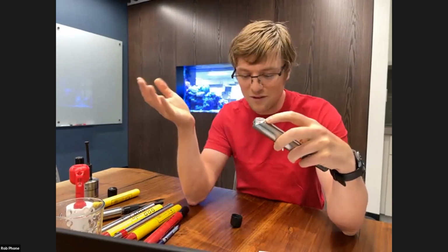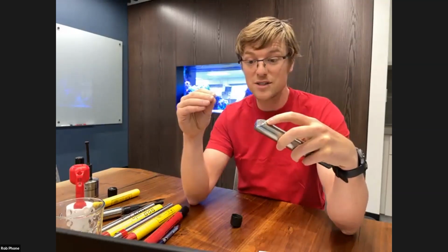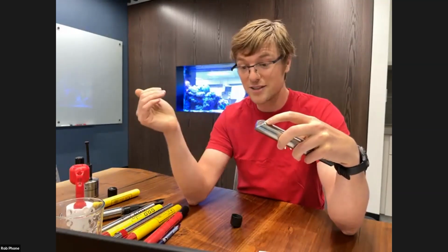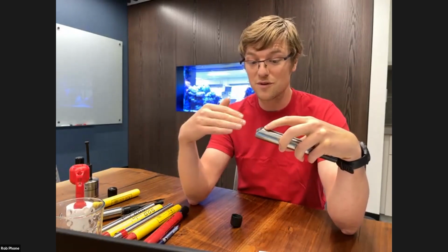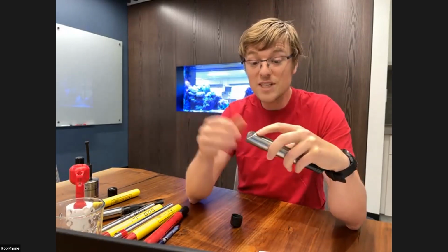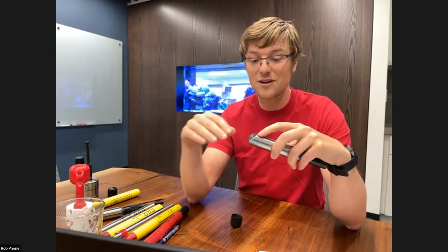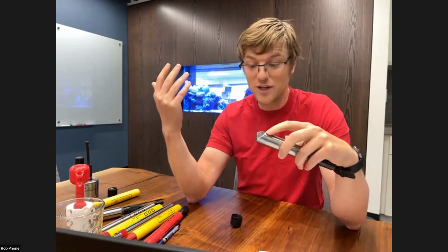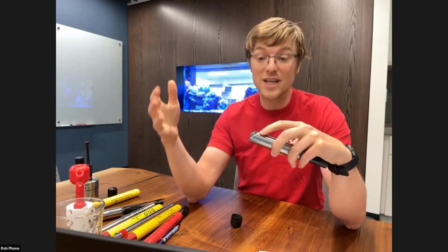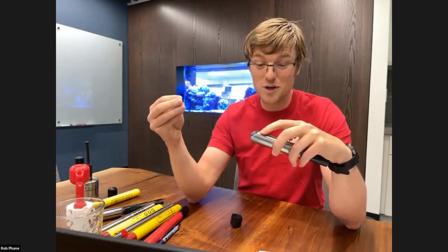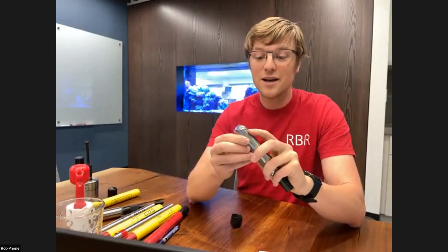Typically to have a faster responding sensor, what you want is a thinner deposit of your active molecule, because the time response is limited by the diffusion of molecules through the active film. So to make the sensor respond faster, you make a thinner film of the active complex, and thus you get a quicker response. But a thinner film means that you have a lot less of the molecule, and so the signal is quite a bit weaker, and so you have higher noise and less sensitivity.